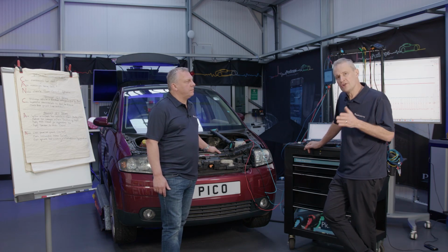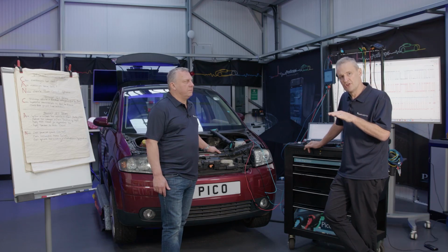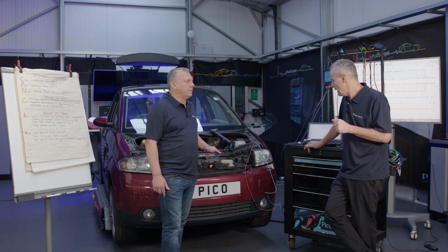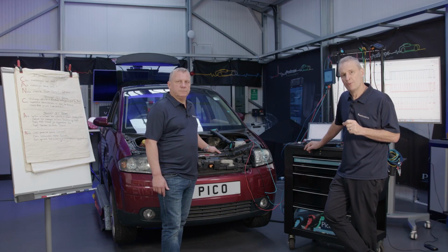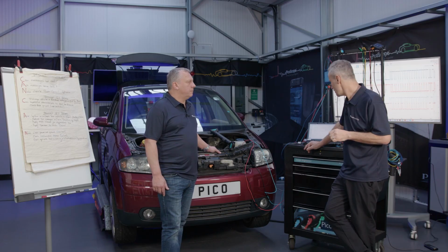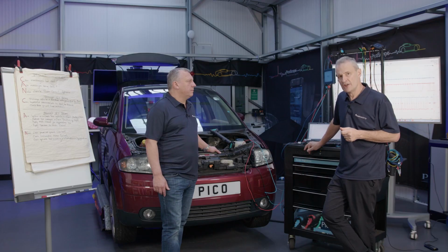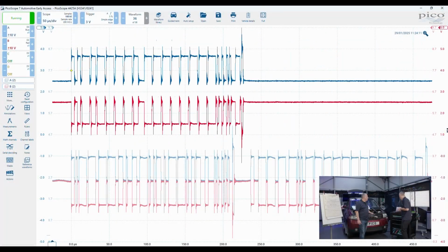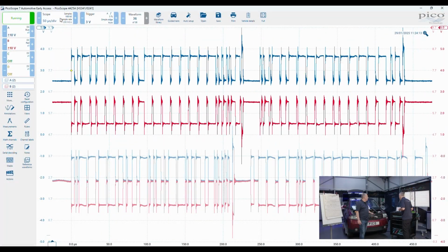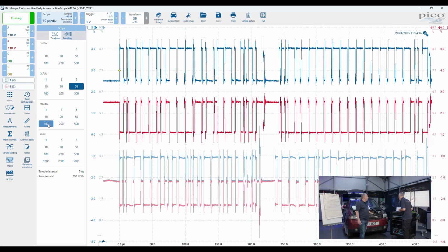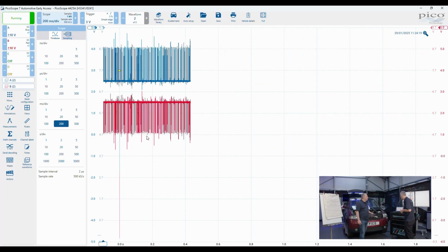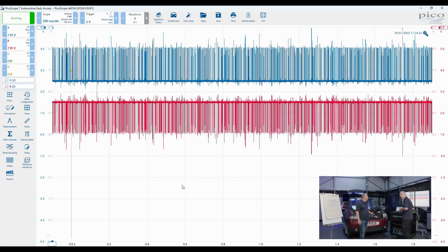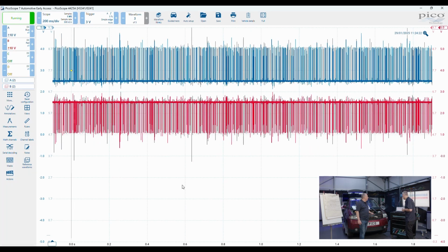What I'd like to do is capture the point where we go ignition off and down to the recessive state, so where messaging stops, and then ultimately capture where it goes to sleep, because that's what's really important. We want to make sure that it does truly go to sleep. So we're going to need to modify the settings to do that. What we'll do is plot this on something like 200 millisecond divisions, which is a neat speed where you can actually see the waveform being drawn in real time. We call that streaming mode.